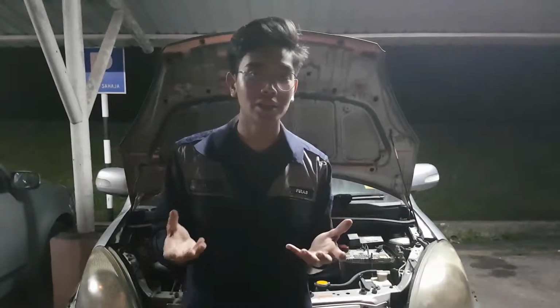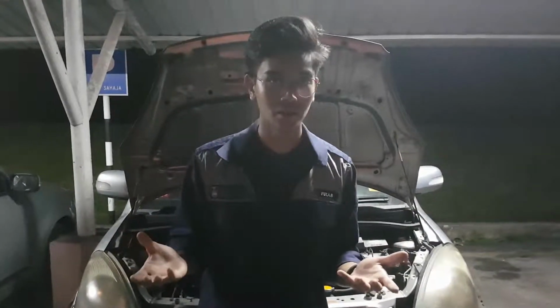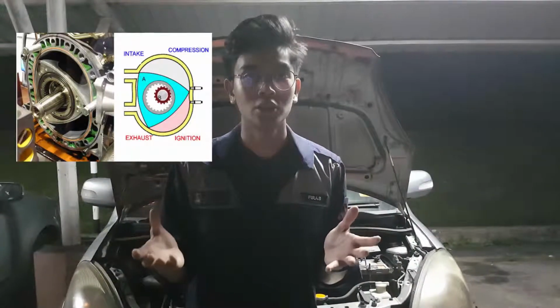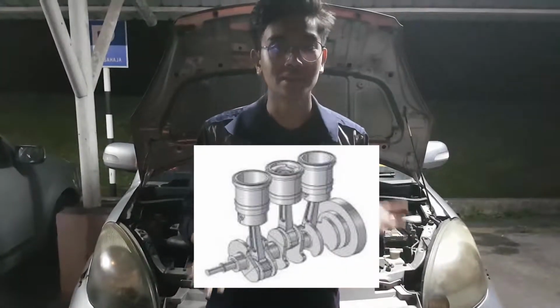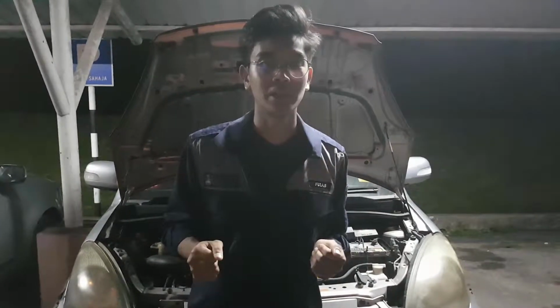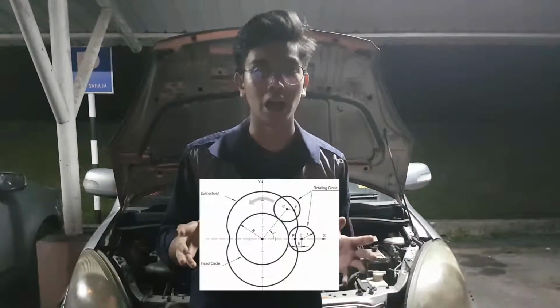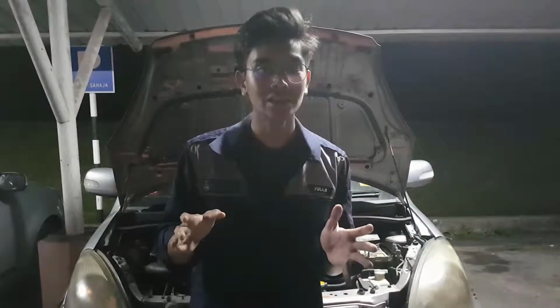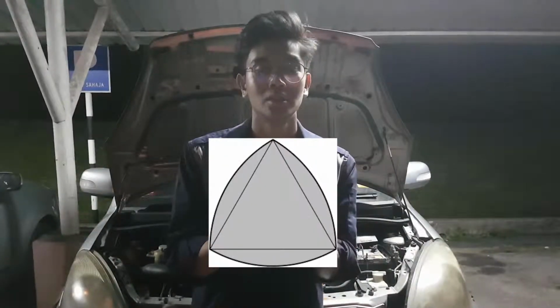Starting off the explanation about the Wankel engine. A Wankel engine is a type of rotary engine. Therefore, it is often referred to as a Wankel rotating engine. It is a type of combustion engine which uses a rotary design to convert pressure into a rotating motion instead of using reciprocating pistons. Its 4-stroke cycle takes place in an oval-like epitrochoid-shaped housing and a rotor that is similar in shape to a Reuleaux triangle. This design delivers smooth, high RPM power from a small compact size.